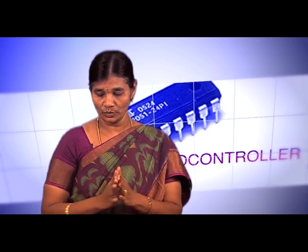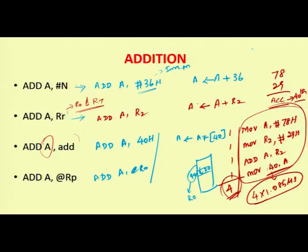So, during the addition, if the result is less than 8 bits, then okay. Suppose it exceeds its size, then sometimes an overflow occurs, right. Suppose here I have taken the numbers 9 plus 9, what will happen? 9 plus 9 in decimal we give as 18, right, but here I have added single digits and I am expecting a single digit, but it gives us 2 digits. Okay. So, this is called an overflow, or it is considered as a carry.